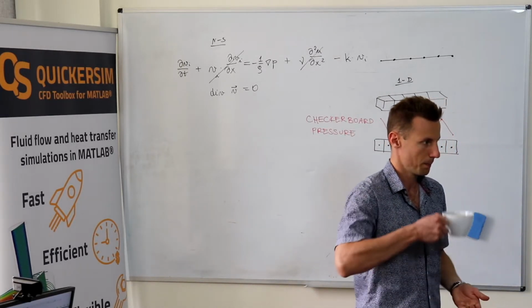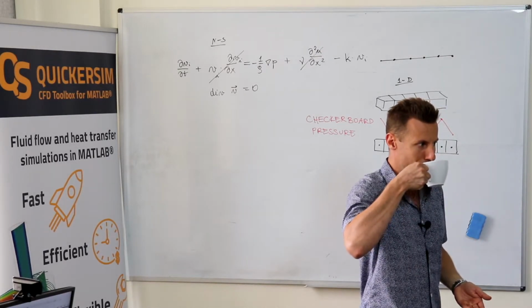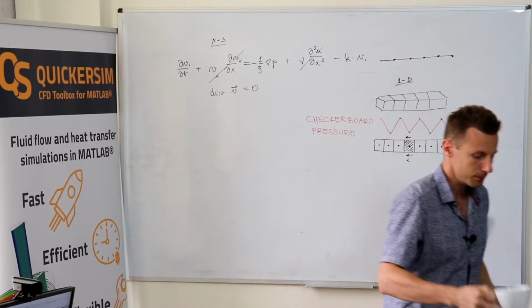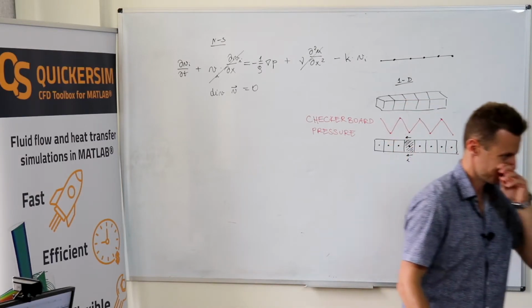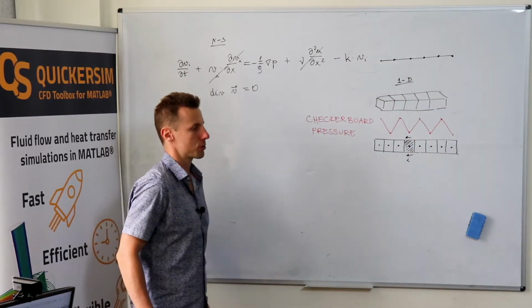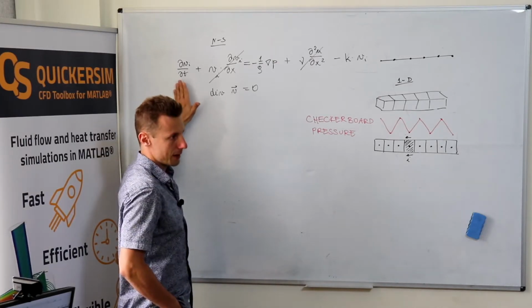Does this problem appear also if we reformulate our equation to a Poisson equation for pressure? No, probably not. But I think you can only generate the Poisson pressure equation if you're dealing with the unsteady case.